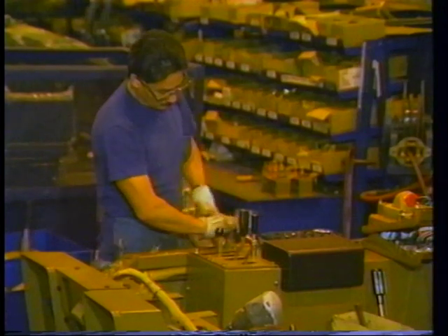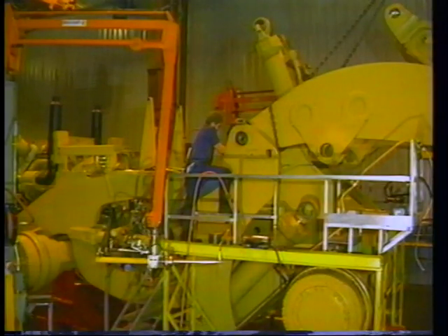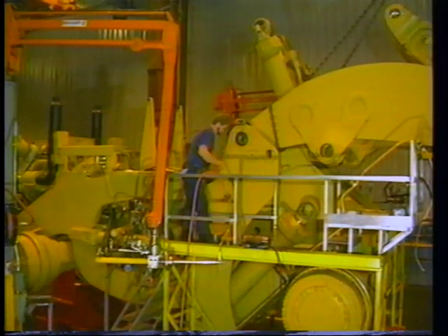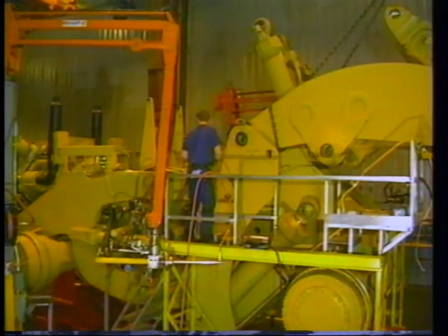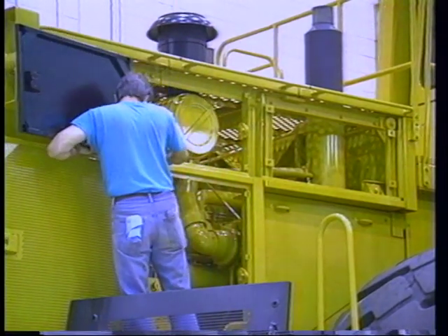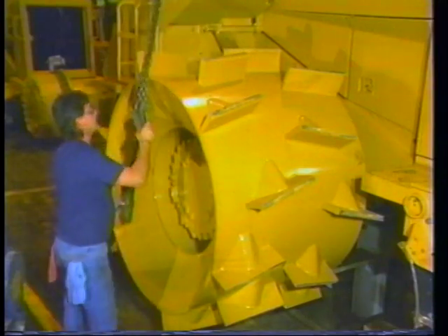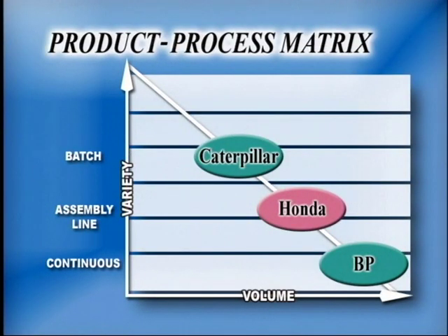Unlike repetitive processing, which depends on a connected workflow, batch processing involves a disconnected production line. Processing is intermittent, with workers coming to the machine rather than the product coming to them. A variety of products produced at relatively low volume with flexible equipment characterize a batch manufacturing process.